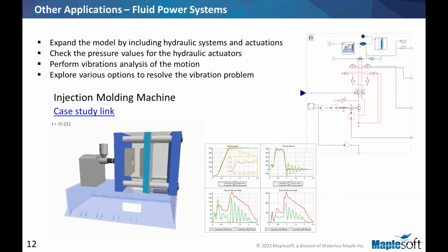So once you create this model, again, we were able to duplicate the vibration. So we knew that the model was a sufficiently accurate representation of the full system, enough that we could investigate the problem of vibrations. And we were able to take this model to automation software, where then the logic, that PLC code, can be tested, modified, maybe new ideas,